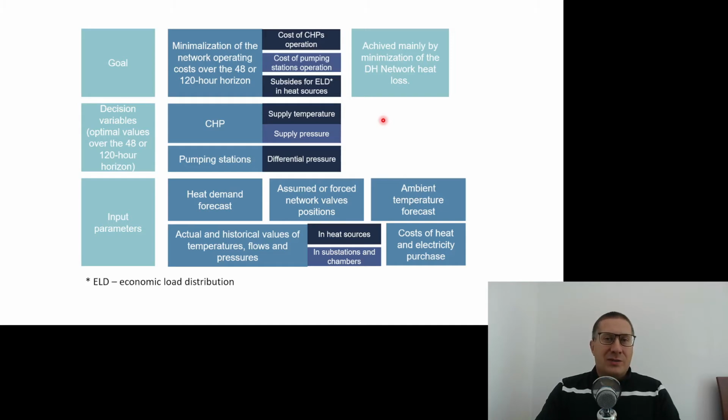What are the decision variables? As I already told, we can change the supply temperature, we can change the supply pressure, and we can play with the differential pressure in pumping stations.